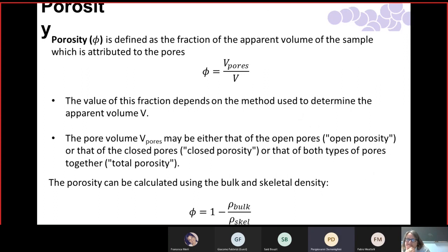Just to add, I was thinking about one thing. You said that the skeleton density is actually equal to the density of aerogel itself, or better, to the silica density itself. But the point is that we know what the upper limit is, because it cannot be more. But the problem is that we cannot exactly know what the right density is because we are overestimating the volume at the end. So we know the upper limit of the density, but we don't know exactly what the real density is, or we can just say that approximately we are very close to the real results if we refer to the silica density.